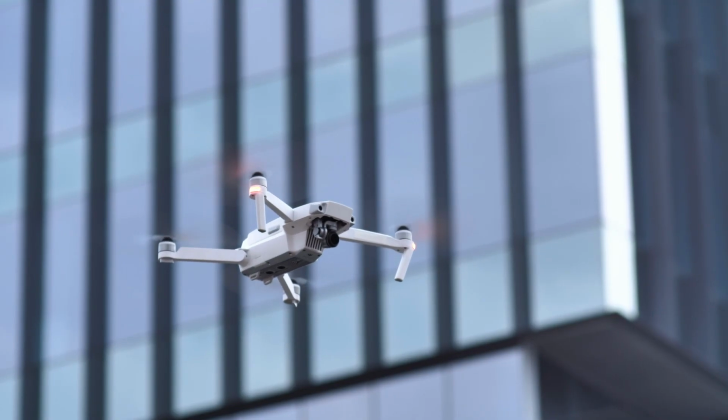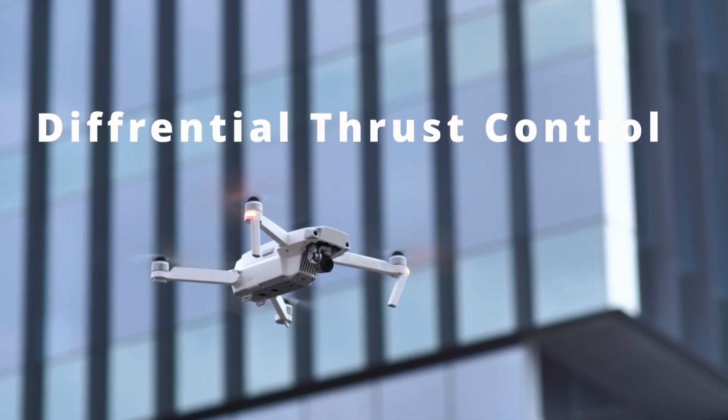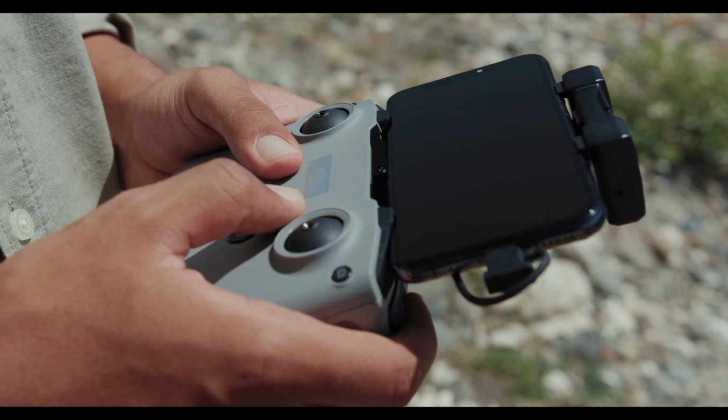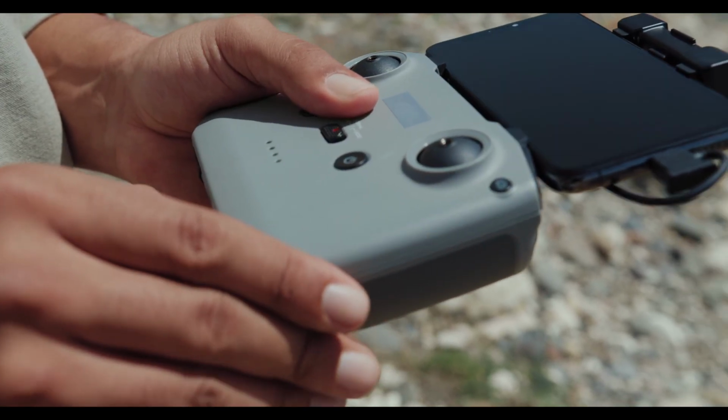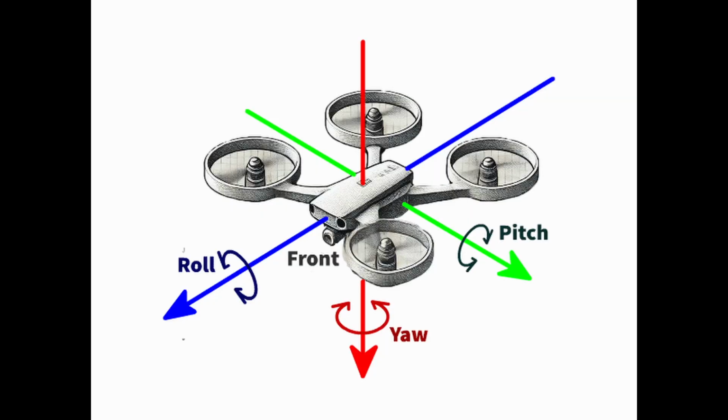Here's why. Differential thrust control. Imagine you're sitting in the control room of a quadcopter. Your flight controller is watching 4 things: throttle, pitch, roll, and yaw. Throttle is simple. You want to go up, spin all 4 motors faster at the same speed. Everything's balanced, so you go straight up.